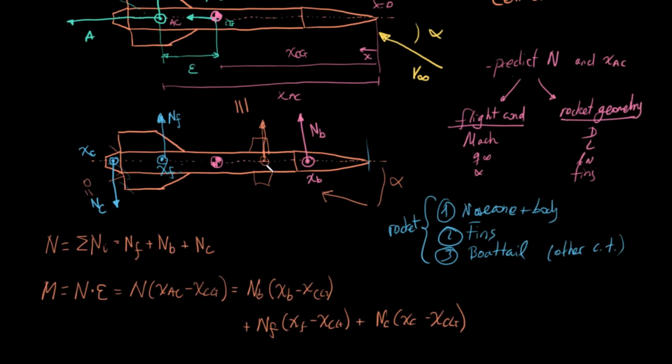So why do you sometimes see fins above, not on the rear side of a rocket? Well, model rockets sometimes copy missiles, and in missiles you do have active control. When we're talking about active control, it's completely another thing. You usually have fins above the center of gravity that are destabilizing, but they move; they're called canards. But we're not going to cover that.